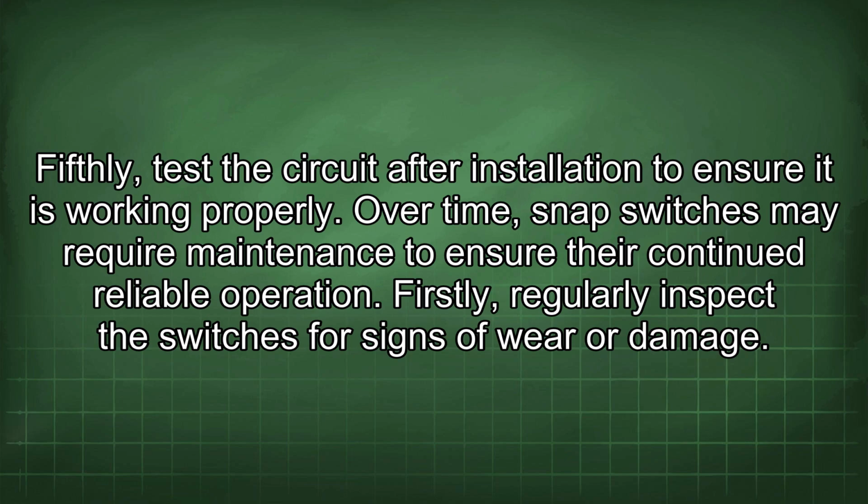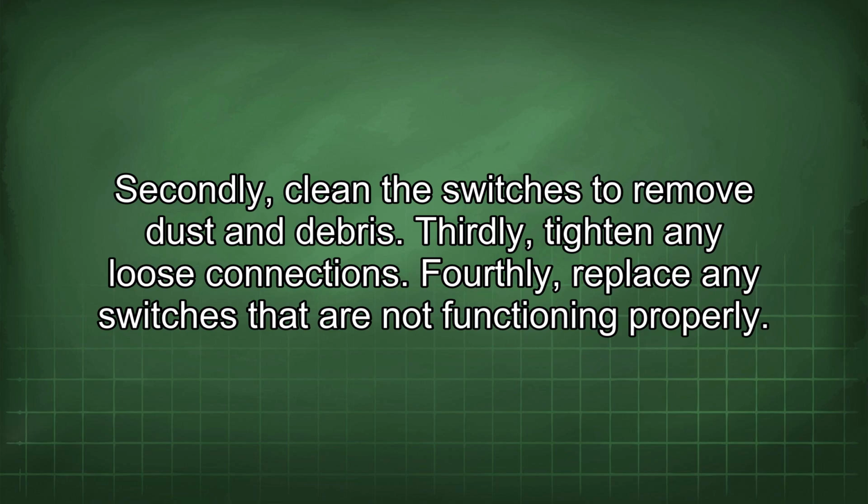Over time, snap switches may require maintenance to ensure their continued reliable operation. Firstly, regularly inspect the switches for signs of wear or damage. Secondly, clean the switches to remove dust and debris. Thirdly, tighten any loose connections. Fourthly, replace any switches that are not functioning properly.